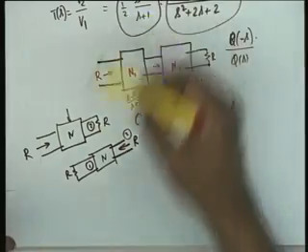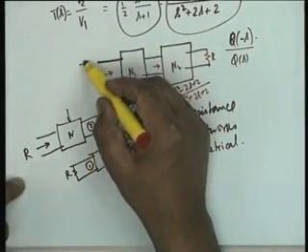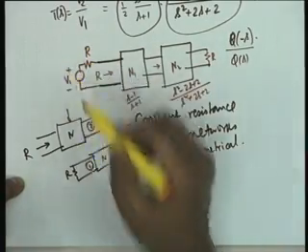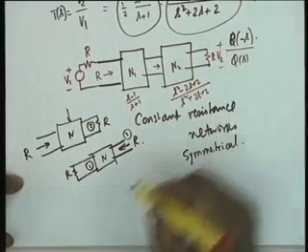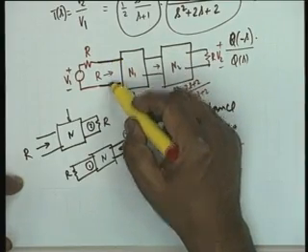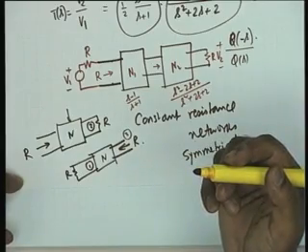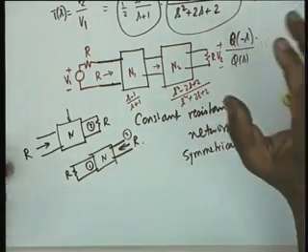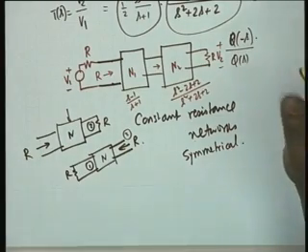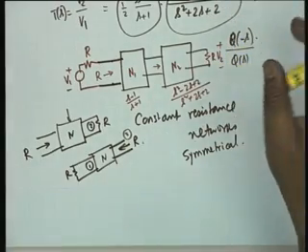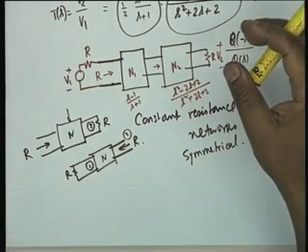And to achieve the factor of half, what we do is we drive it by a source of internal resistance R. All right. Then what is the voltage here? Half of V1. So the factor half is realized. Do you understand the importance of constant resistance networks? That if we have constant resistance networks, then we can realize a complicated transfer function by decomposing it into simpler ones, and the synthesis in most of the cases is obvious just by inspection.